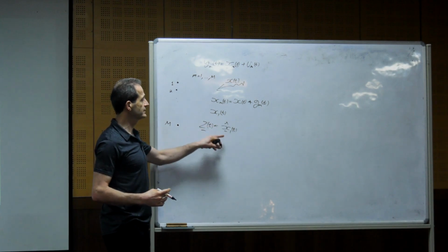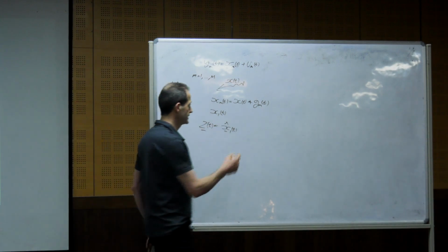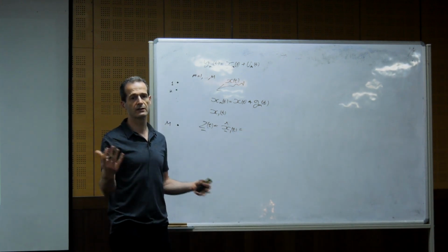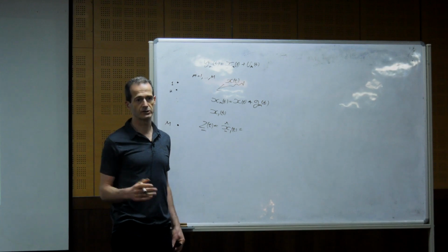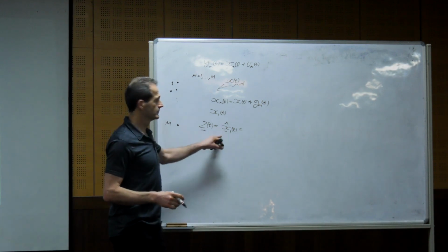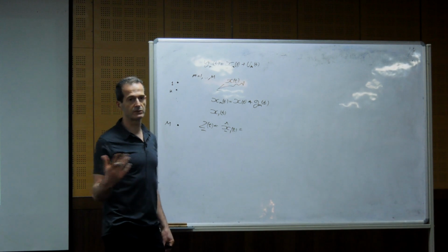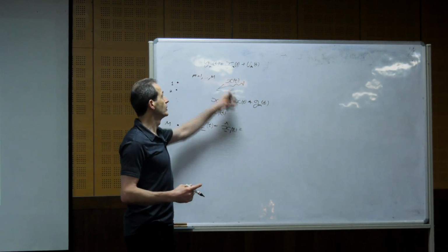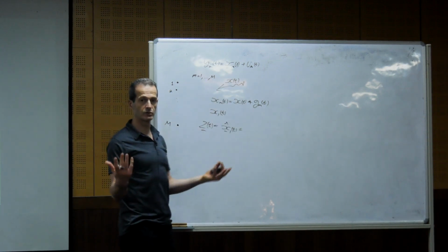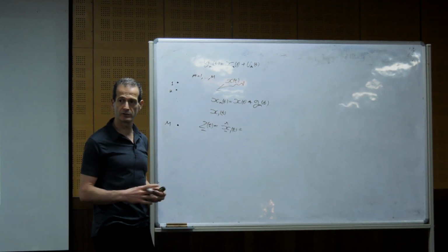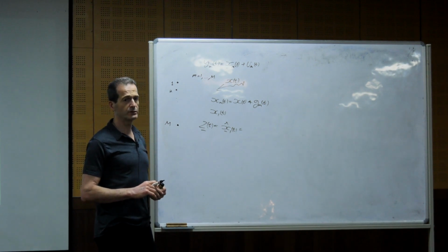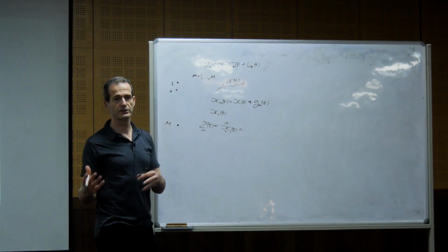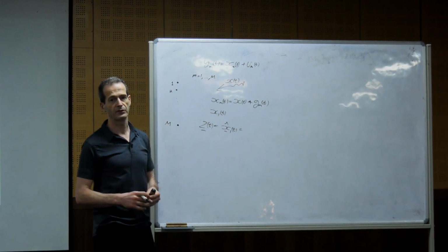So this vector is an estimate of the desired signal in the reference sensor, and of course it includes all the reflections, reverberation. Maybe afterwards you want to do some de-reverberation if you can, or you can do an estimate of the original signal. So it's joint de-reverberation and noise reduction. If you're interested in this method, you can just look for joint de-reverberation and noise reduction. You will get some methods.